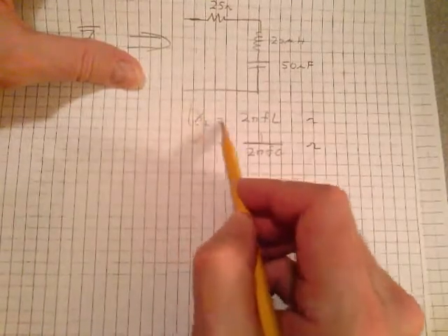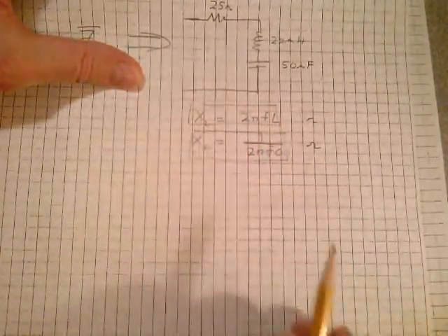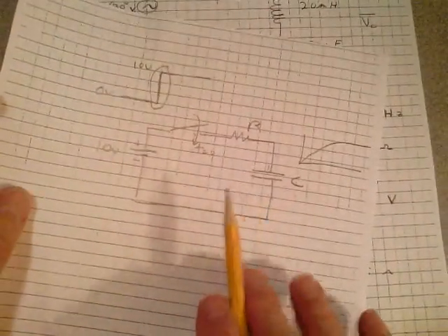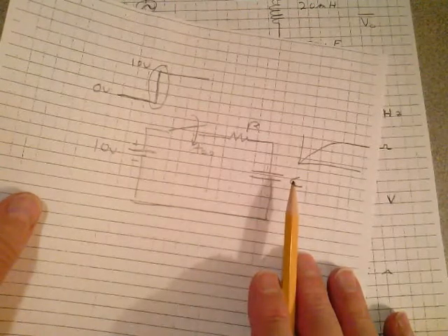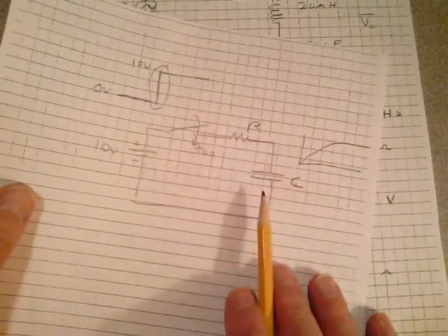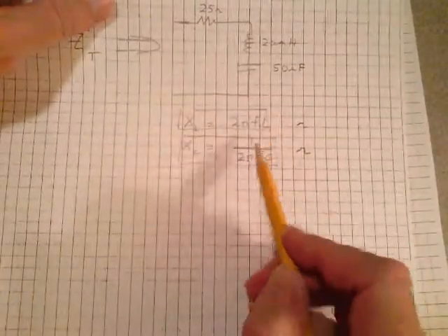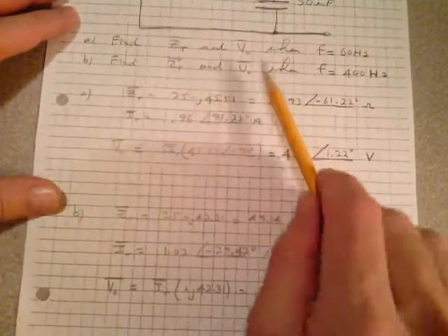So both this function and these equations tie into the fact that when you first throw switches like this, inductors look like an open circuit and capacitors look like a short circuit. And then at t equals infinity, the inductor looks like a short circuit and the capacitor looks like an open circuit. You go back and look at it all in terms of these equations right here. You have to think about that. All right, let's get back to this problem and finish it up now.